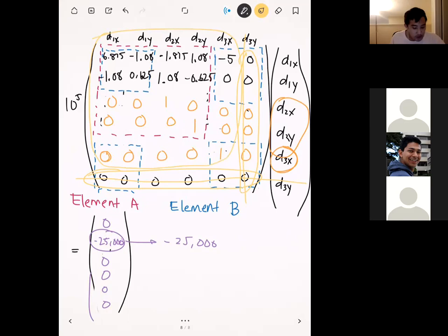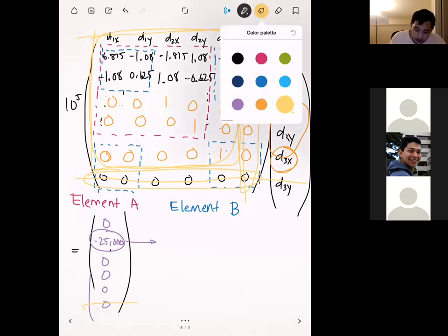And so this actually makes our system a little bit smaller. Let me cross out that guy too. Instead of a 6x6, now we have this 5x5 system. What you can do now is plug this 5x5 system into MATLAB and use that to solve for the displacements. If you do that, we can go ahead and plug these in and solve. And what we get is the following.